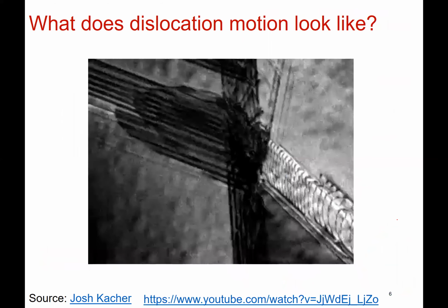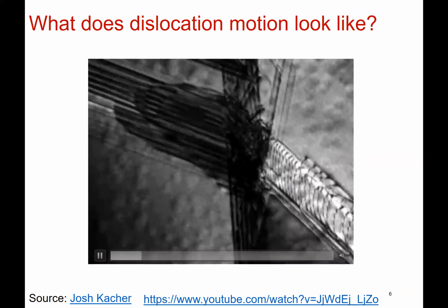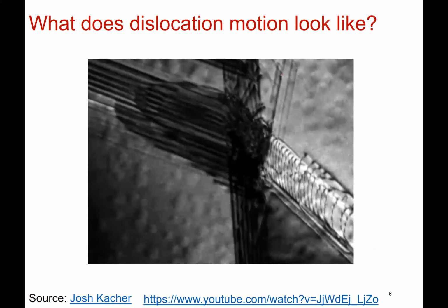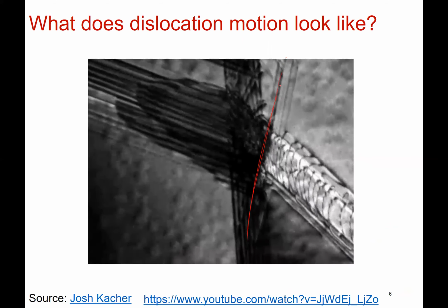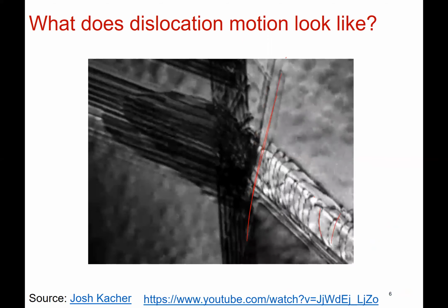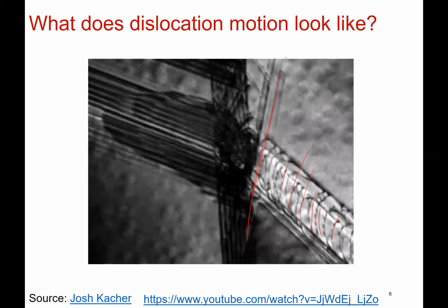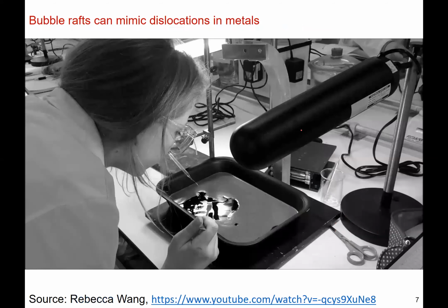And so that is this example here. Do you see those lines of dislocations when they come to this part right here? They actually can be annihilated or stopped, right? And we can actually measure the angle of these dislocations in the single crystal throughout the experiment. So this is really neat, and it's more than neat. It's technologically advanced to be able to see the dislocations move and how we can pin them over time.